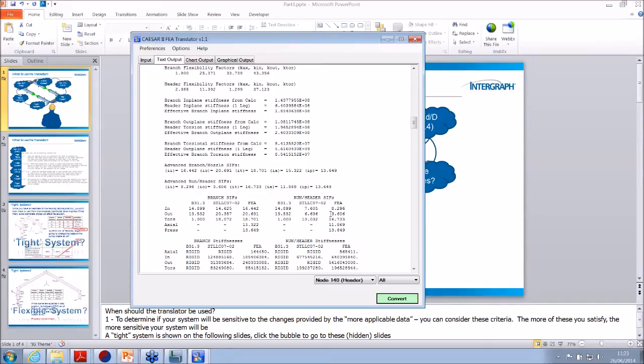These have now dropped to 8 and 3. So the in-plane SIF is not far off half the original SIF, and the out-plane SIF is only about 18% of the original. So these reductions in SIFs should make quite a bit of a difference to the sustained load case, which was failing due to, we believe, the high intensification factors.